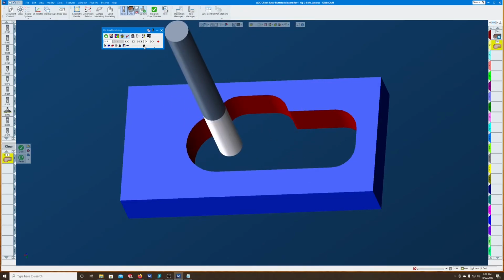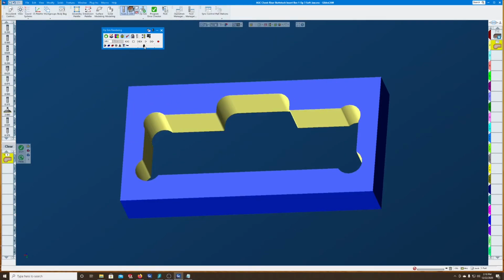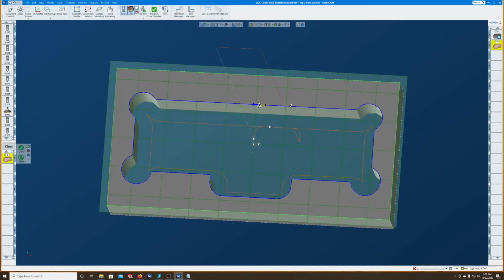And what this software will tell us, it gives us an idea just to visualize how the cutting should occur. And also, if the end mill is going to slam into the part, the software is smart enough to give you a warning to let you know that it's going to gouge it. You could break a tool, things along those lines. And so once we're satisfied with our tool path, then what we'll do is tell the software to generate what's called G code.